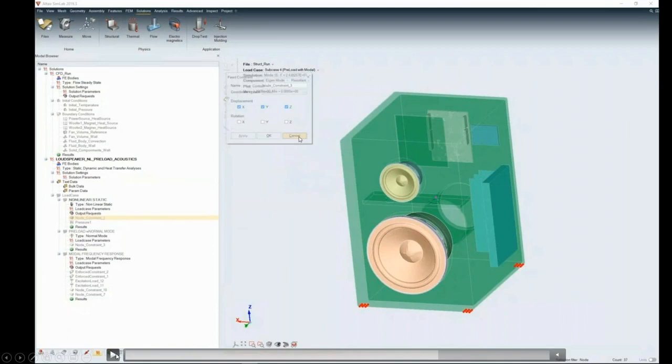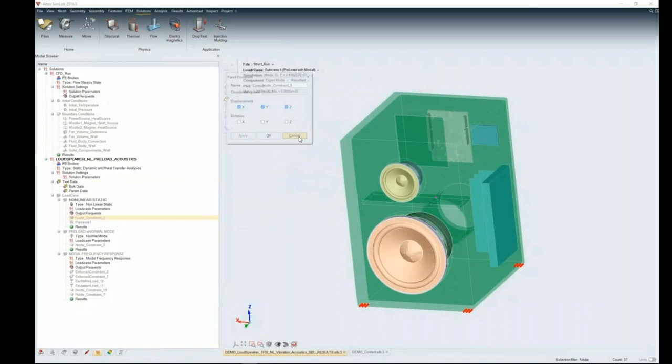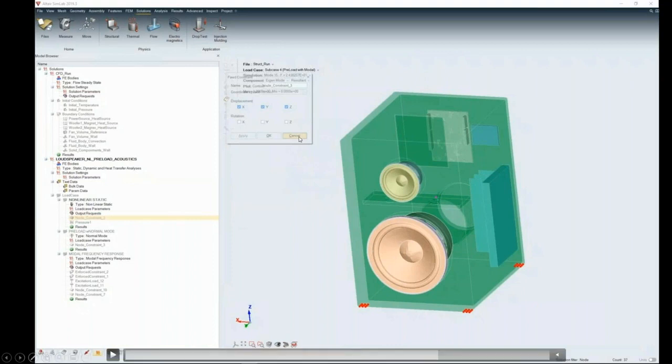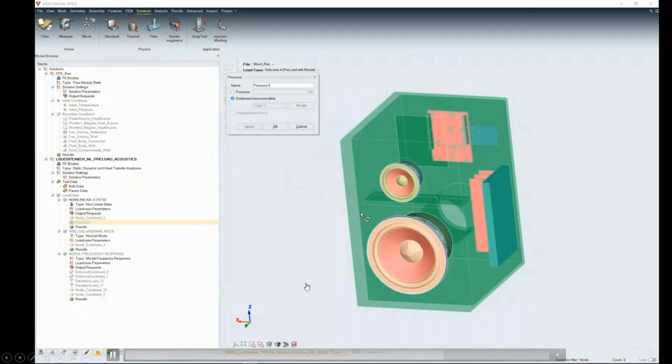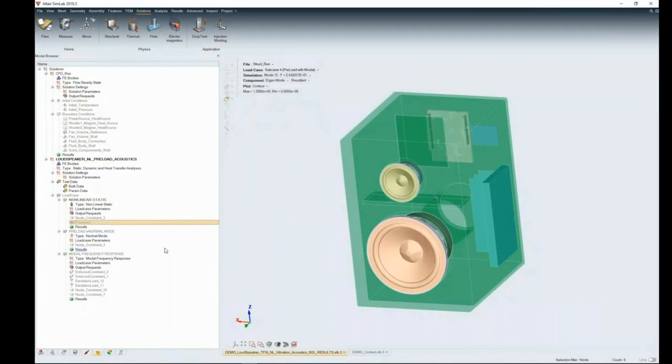The good part about SimLab is that once you start setting up these models, if any definition is not enabled, it will never allow you to run the model itself. Those are the defaults which it needs from the user to be incorporated. So here you can see the boundary conditions. For nonlinear analysis, that is a must. For modal analysis, that's optional, because it may think that you're doing a free analysis versus a constrained vibration analysis there. So these are pretty nicely included.